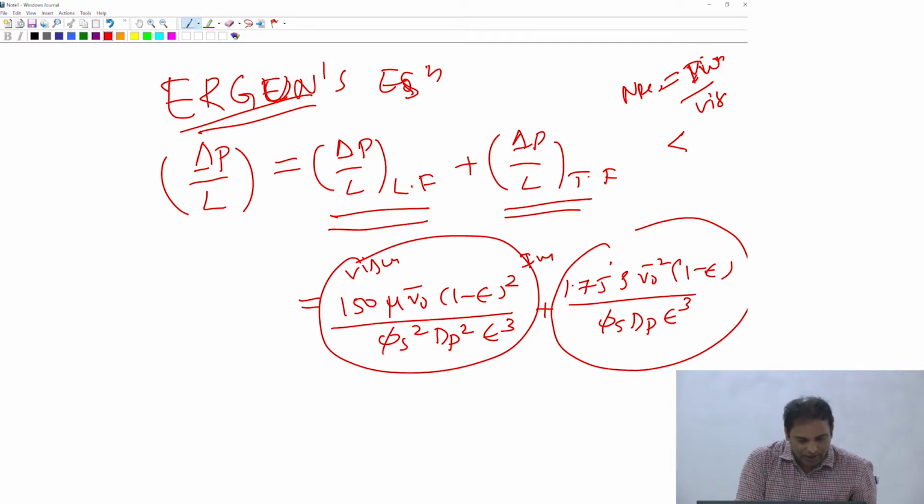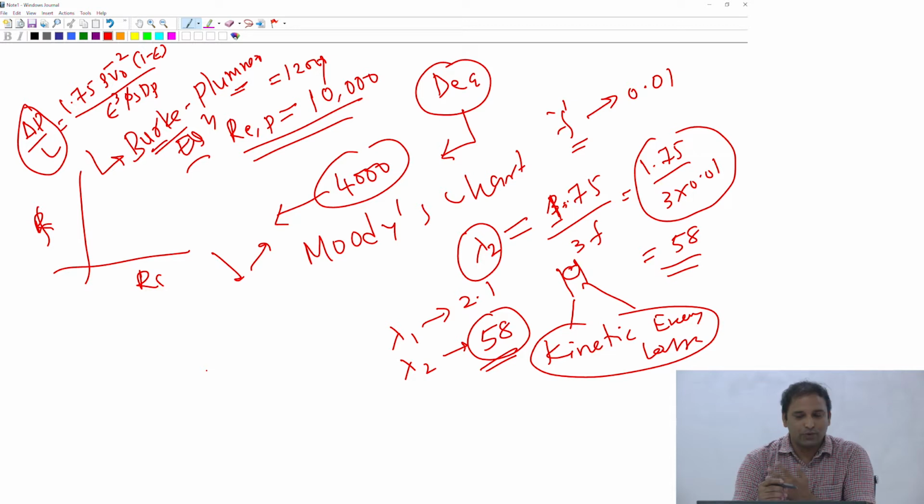I just took a case that was actually given in the book, but the idea is this. If I want to get F, the friction factor, and use a Moody chart, I should know the Reynolds number for the flow through a pipe. So if the flow is occurring in turbulent flow conditions in the packed bed, I find out the Reynolds number for that condition.